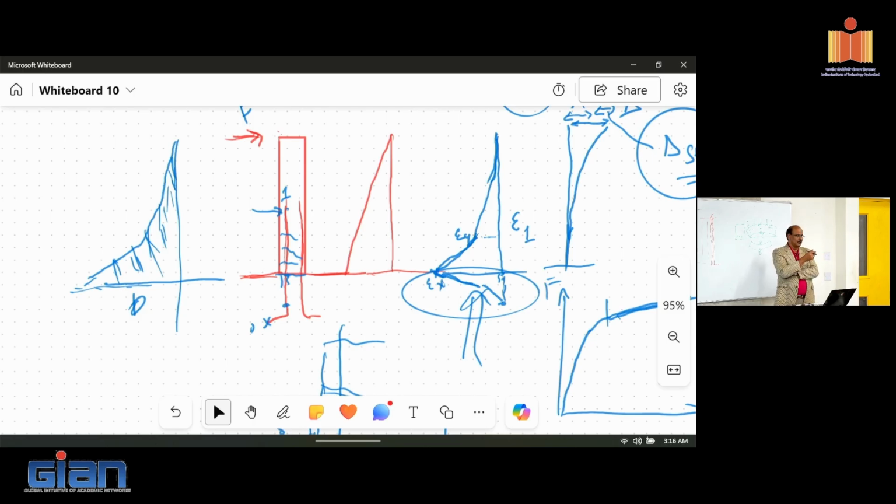If you look at the plastification that happens in columns, walls, and beam ends, they quantify it to be in the 25 to 35% range. So traditionally, we say we need roughly 30% damping in the structure for it to survive earthquakes.